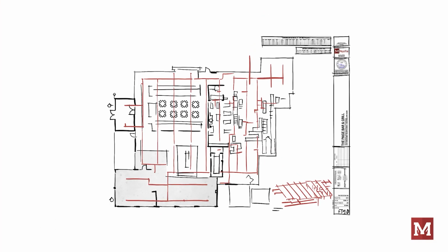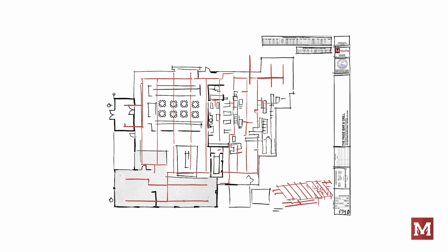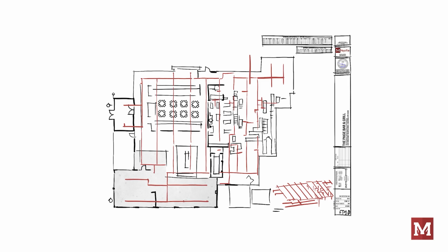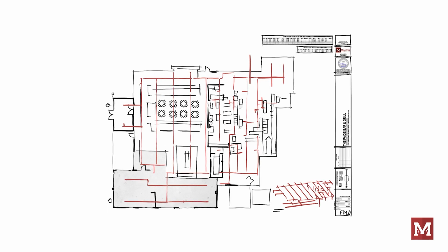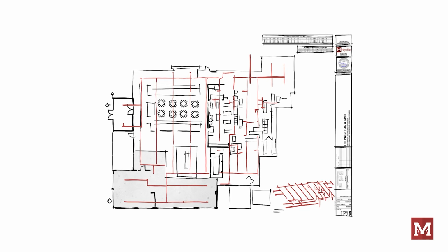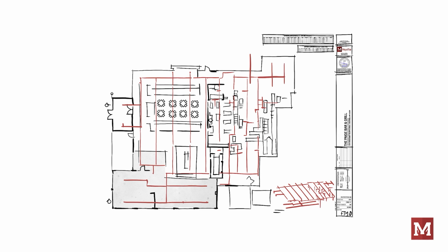Isometric drawings may or may not be in the set of building plans. An isometric drawing shows the building or a building system in an oblique angle in 3D. In our fire protection drawings, there is no requirement in NFPA 13 to show an isometric view of our system or systems, but I find it helpful to include this in our field plans for the installers on more challenging or technical systems like those protecting high-piled storage.